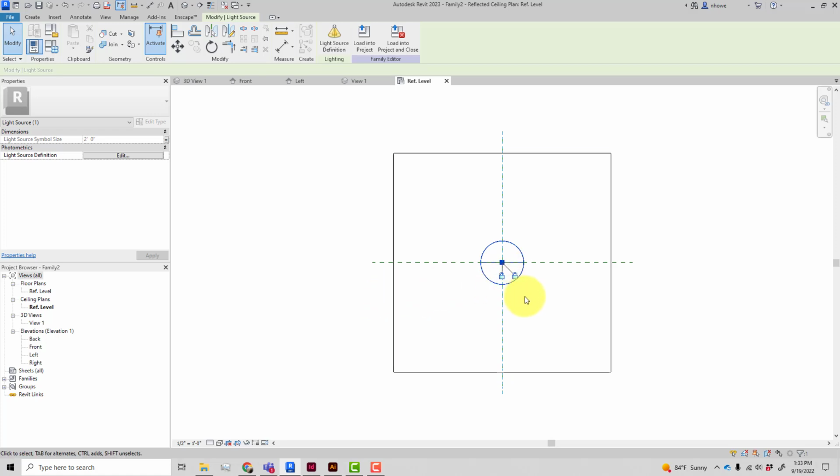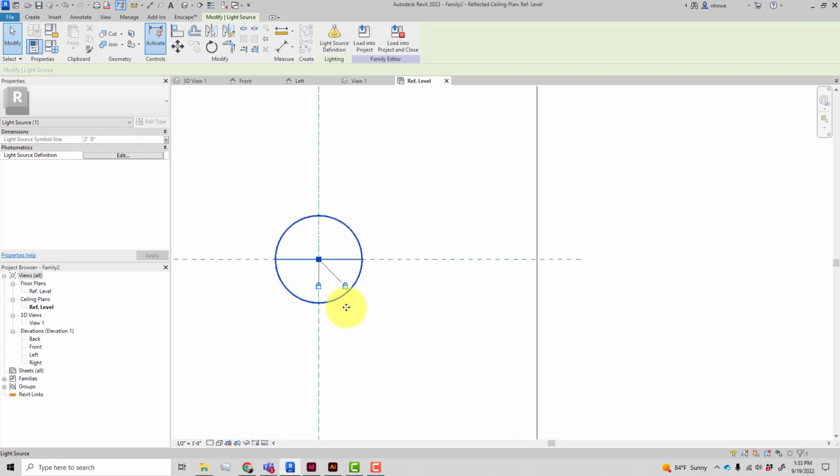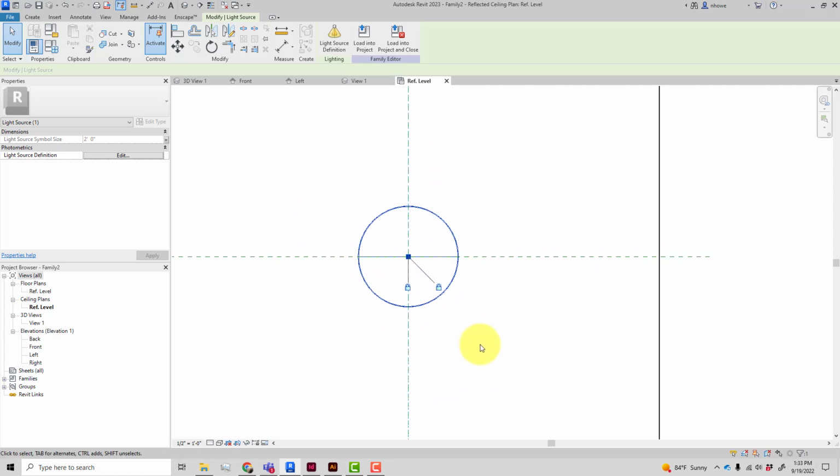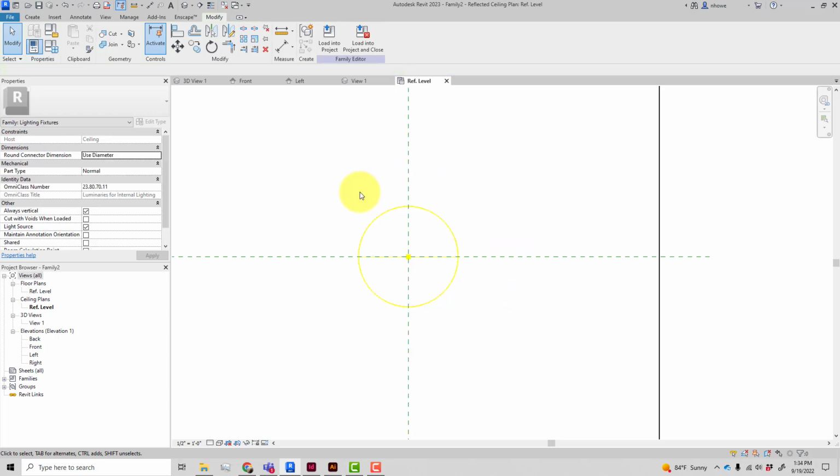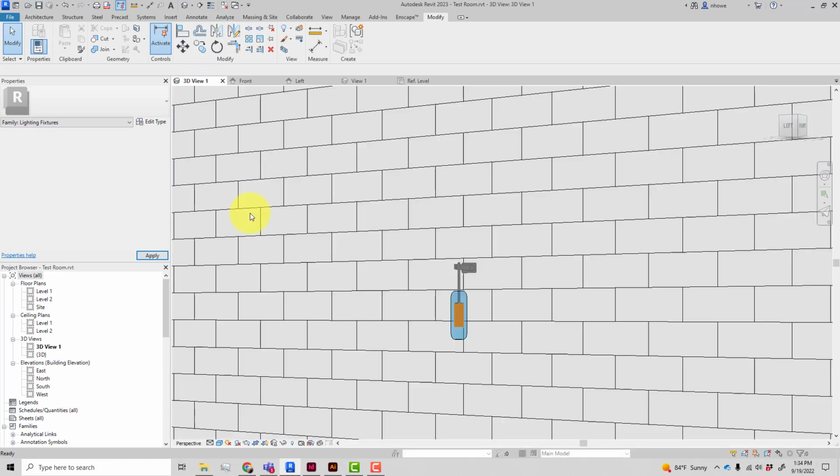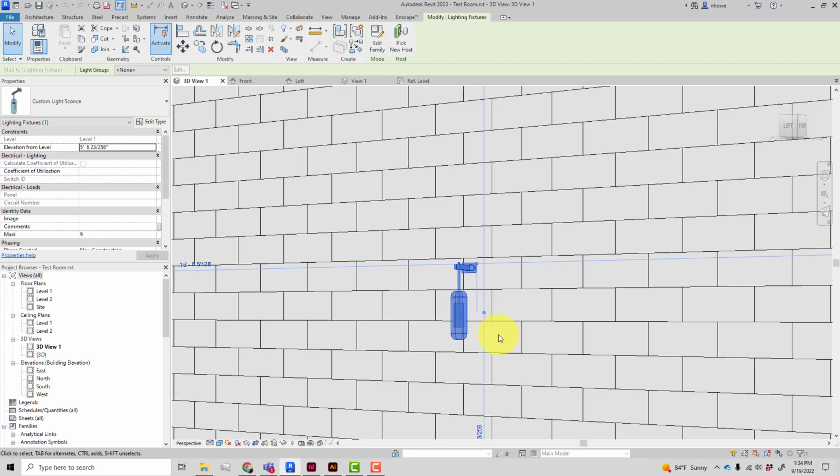But here I also want to drive home that Revit's a pretty good modeling software, so it may be worth it, and there are some advantages to modeling in Revit as opposed to Rhino. Here, the sconce is going to remain pretty static, all we really needed to define is how high it is on the wall.